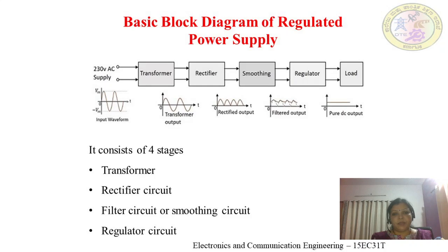There are various types of rectifiers, such as the single diode based half wave rectifier, and the full wave rectifier. In full wave rectifiers we find two types, the center tap full wave rectifier and the bridge type full wave rectifier. The rectifier's function is to convert AC input to DC, so it produces a pulsating DC as shown in the waveform after the rectifier output.